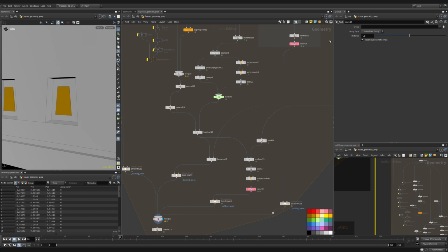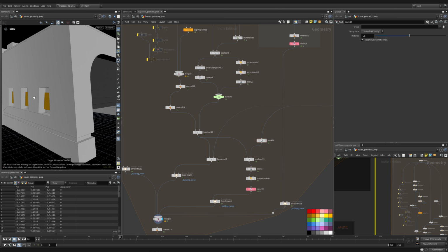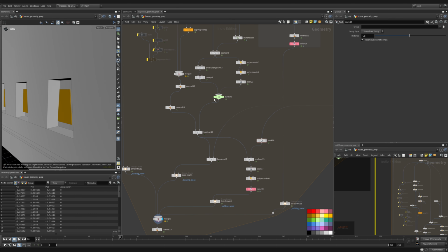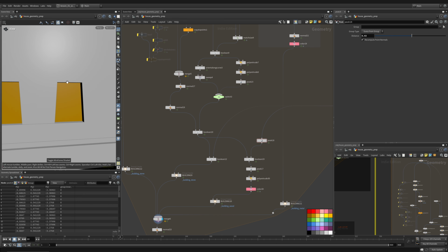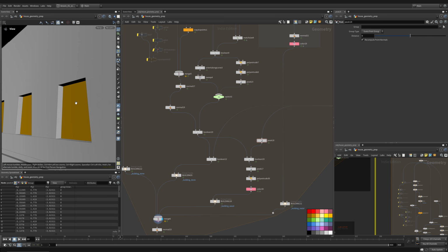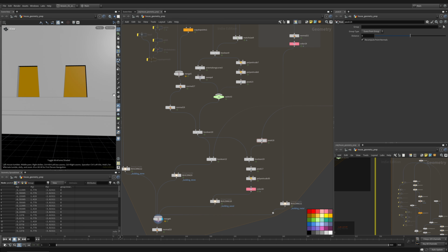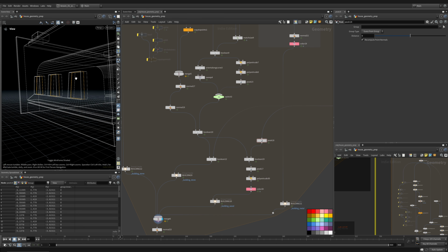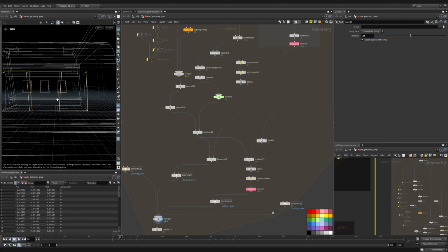All right, 0.2. So I could shrink that so it's smaller than my window, but because I'm trying to create like a shutter or a window cover, I wanted that to always be bigger than the window. And again, W is going to wireframe. And you see it's the exact same size when it's 0, and it most likely wouldn't have any issues. But maybe if there were lights inside the garage and this window was cut all the way through, then we would see little artifacts in between or shading artifacts. So I just wanted to increase it with a little bit of an intersection here to intentionally block all that light.